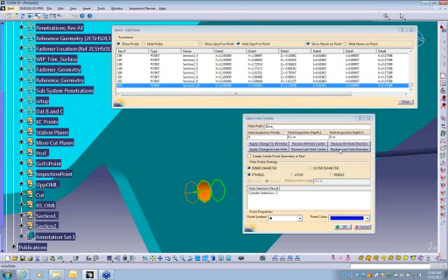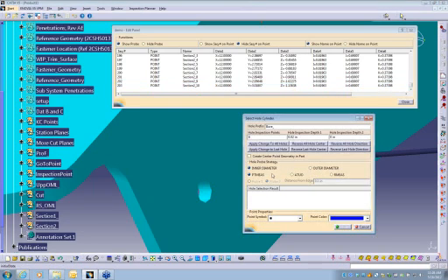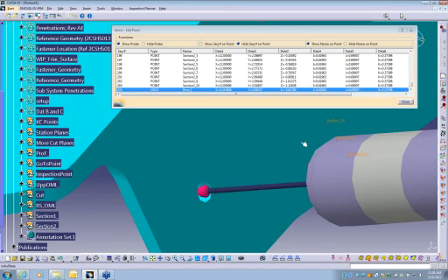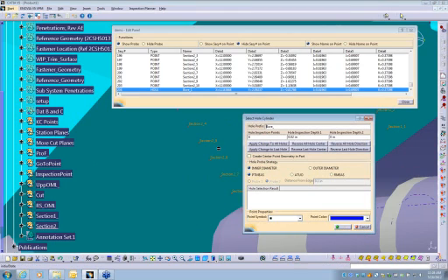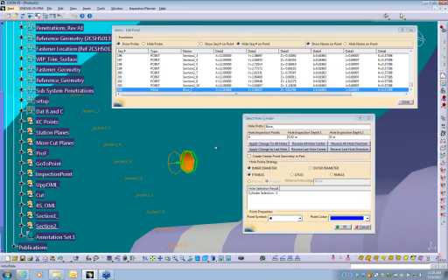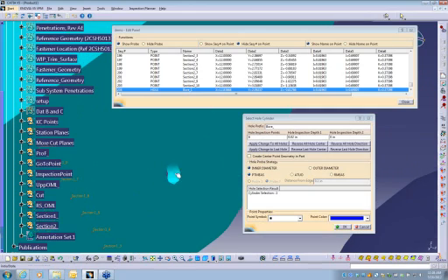I want to reverse the last hole. Looks like I'm too deep. So let's go to there. Cancel that. Let me change that to 20. Pick that. Reverse it. You can see where we're going to be there. We'll say OK. And we come over here. Do the same thing. You can just pick that and then pick that and reverse all holes.